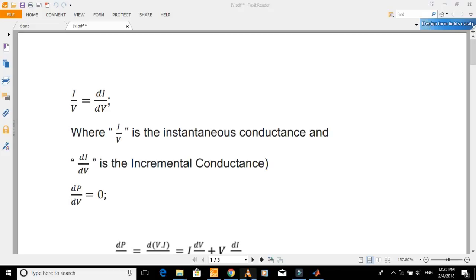In this video tutorial you will learn the basic concept of incremental conductance MPPT for solar PV and its implementation in Simulink MATLAB. Incremental conductance MPPT was developed to overcome the drawbacks of the perturb and observe MPPT technique. The incremental conductance method computes the maximum power point by comparing the incremental conductance to the instantaneous conductance of the solar PV array. When these two are the same, the output voltage is the MPP voltage. The controller maintains this voltage until the irradiation changes, and the process is repeated.